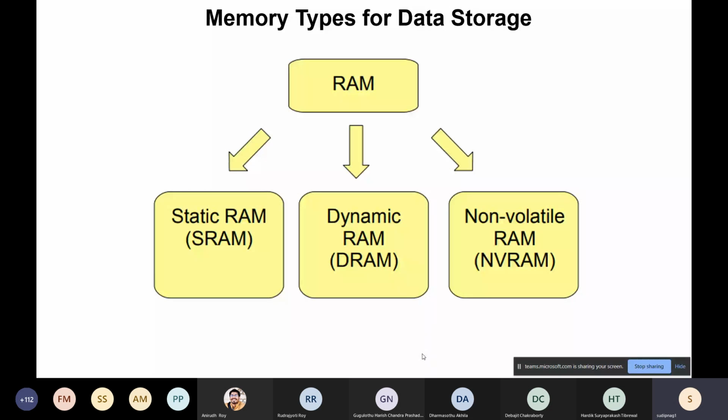That means your data is wrong. That's a problem in DRAM, so to combat that, there is refreshing, meaning dynamic updating is happening. It's like your mobile phone battery is all the time discharging and you are recharging from time to time. The same analogy works at a much faster rate for DRAMs. But at the same time, DRAM takes small space, which is a huge advantage, and that's why it became so popular. And there are different generations of DRAM.